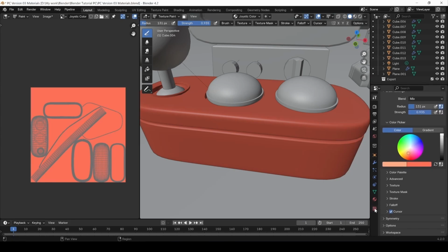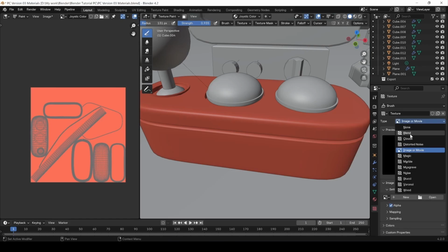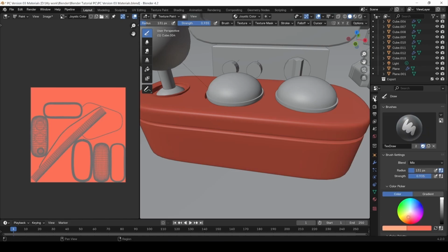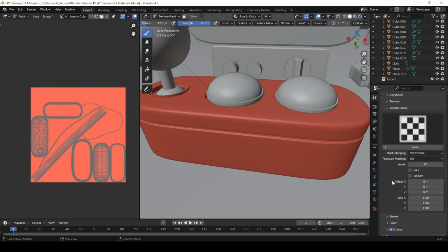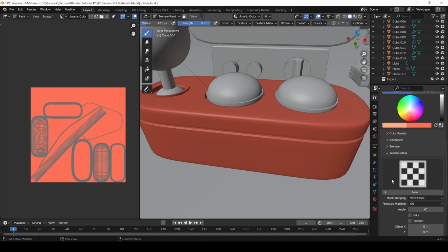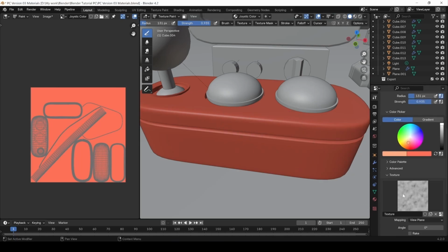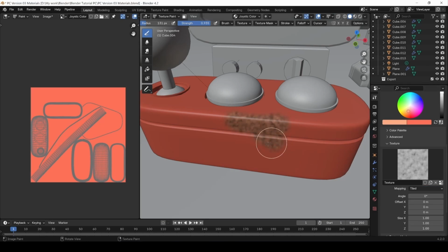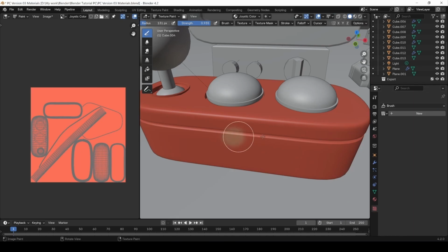And if you go to texture down here and you do a new texture, you can choose, for example, a cloud. Now, if you go back and go to the texture, you will find that you are using the cloud, and if you color, you are coloring with the cloud. Of course, you can just change it here to make it tiled or 3D or whatever you want. Okay, so go back. Let's actually delete this and get it back as it was.